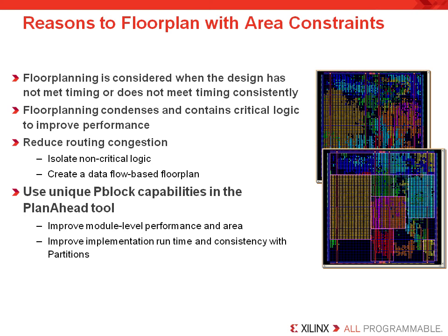Floor planning has a much wider approach. It can range from a more detailed approach, such as placing individual logic elements of a critical path to a specific site on the chip, to a more abstract approach, like constraining levels of hierarchy to specific regions on the chip. Some design teams may spend time floor planning a design before the first iteration through place and route. Others may take a wait and see approach, electing to wait until a problem is identified before floor planning.